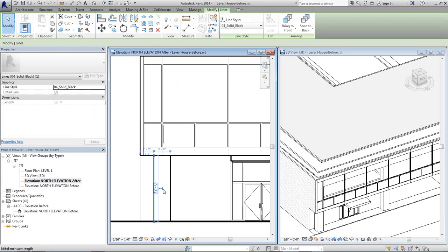So here you can see we're starting to develop a little bit of line weight, a little bit of understanding of depth. Now we're doing that, as I mentioned, with detail lines. There's another really great way to manipulate these line weights, and that's using the line work tool, which for me was a sort of hidden tool. It took me a while to finally find, and I think it's a pretty awesome tool. It very quickly allows you to override the line styles for a modeled element. So for example, let me just show you how it works. When you select this, it's under Modify, by the way.